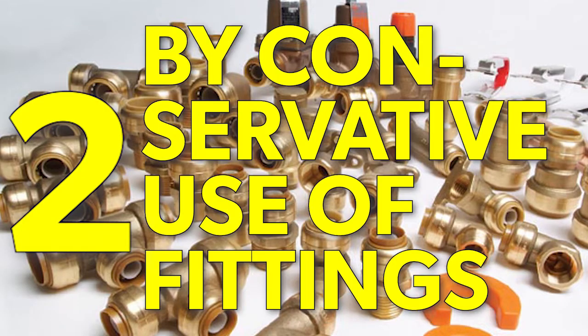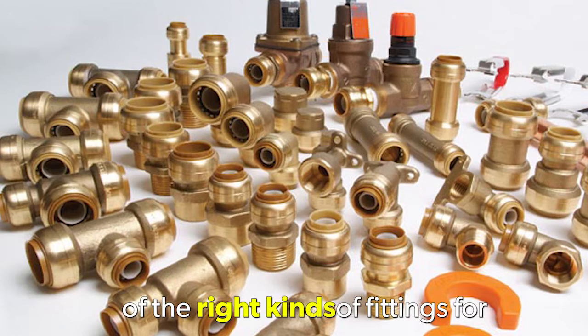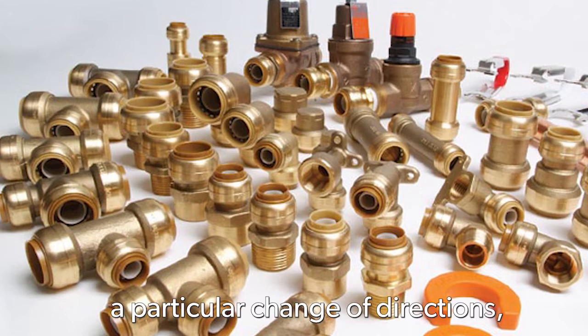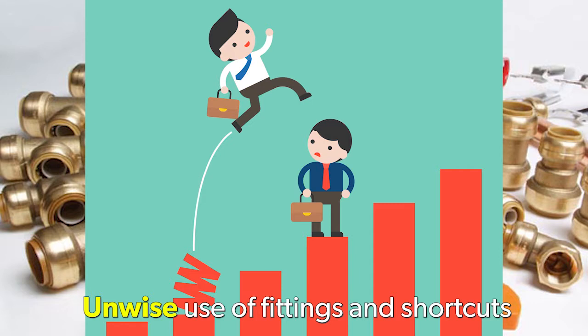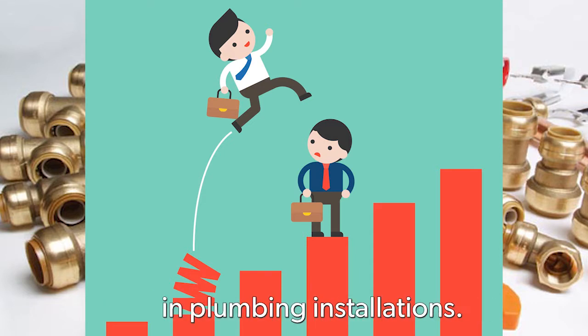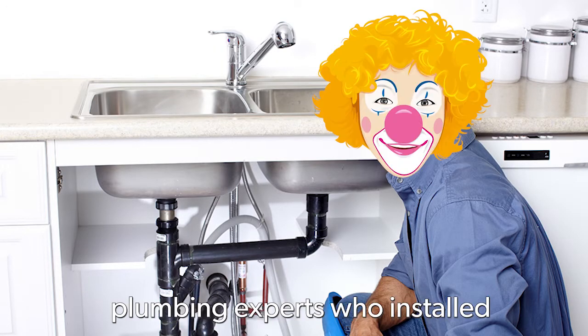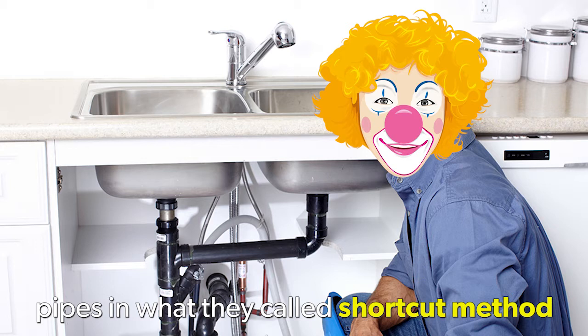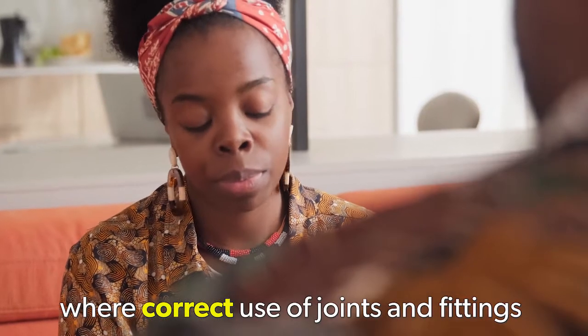2. The conservative use of fittings. It refers to the right choice of the right kind of fittings for a particular change of directions, turns, or offsets. Unwise use of fittings and shortcuts that do not allow smooth passage of waste should not be allowed in plumbing installations. There were many self-proclaimed plumbing experts who installed pipes in what they called shortcut method, where correct use of joints and fittings were not properly observed.